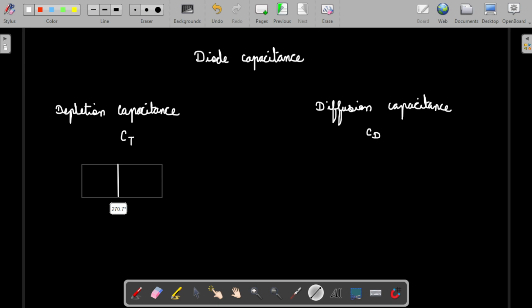So this is simple separation. So this is depletion region separation. Okay. So if we take the thing here, because of these things, there will be some capacitance effect acting between these two. Here there will be some capacitance acting. Okay, so this is how we will be taking. So this is only when it is reverse biased. So only in reverse bias condition, depletion capacitance will act.